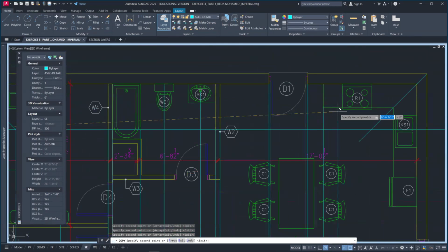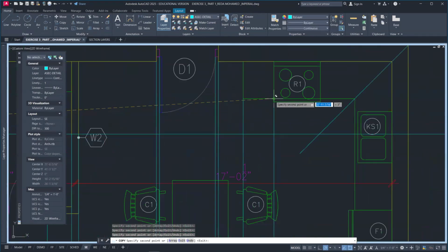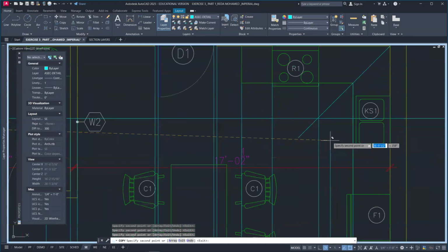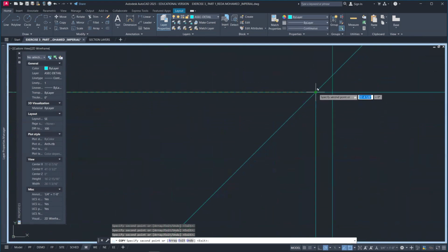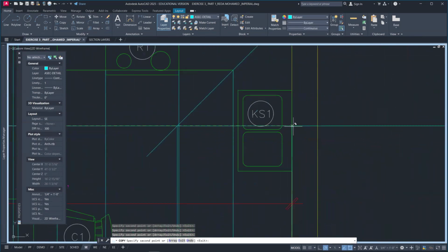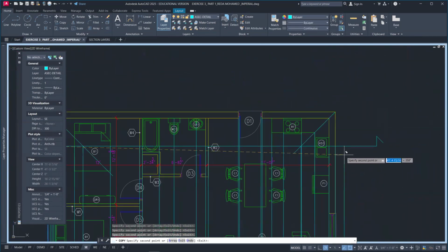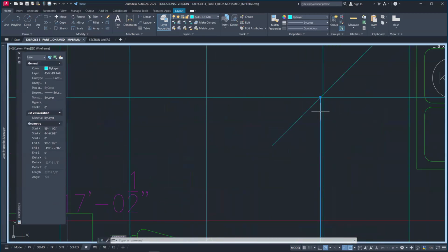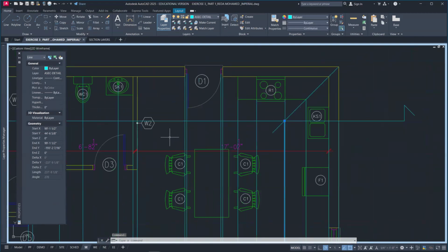and then the edge of the counter, the placement of the range, and then the counter itself. This one here, I do need, okay. And then the walls here, just to show its alignment to the building. Okay, now there's too many projection lines and at times it's hard to know what they are when we are in the section view where we're drawing it. So what I can do is select the lines and change the colors.